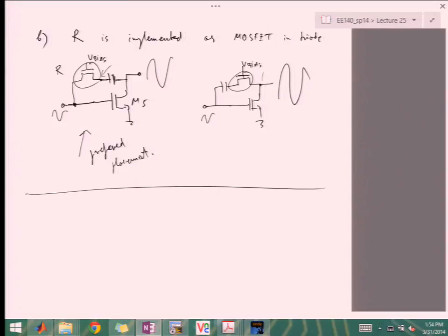But there's no sort of one recipe, it depends on the specs. What's your phase margin, what's your settling time, et cetera. But this just gives you a feel of what the choice of that value for R will do to the circuit, right? It will either make it a left half plane 0, get it to be completely eliminated from the picture by going to infinity, or sitting right around your second pole.